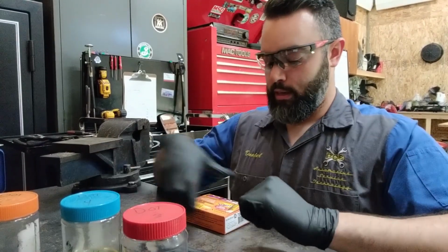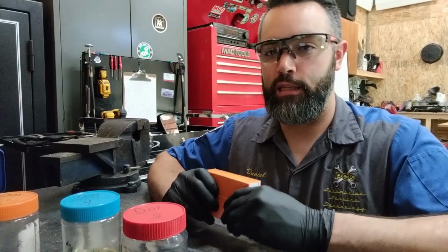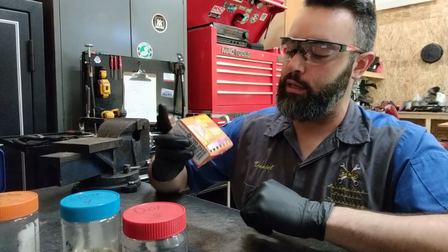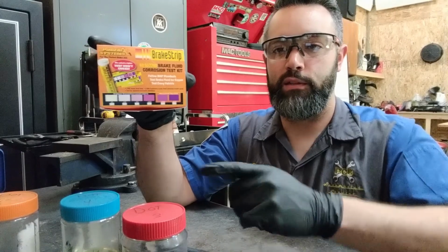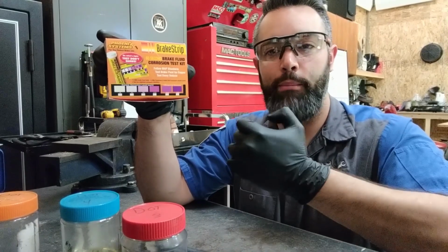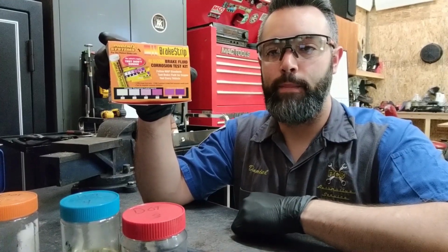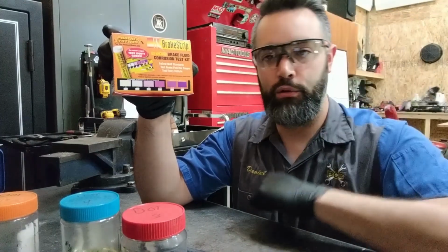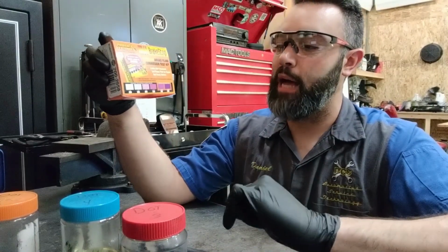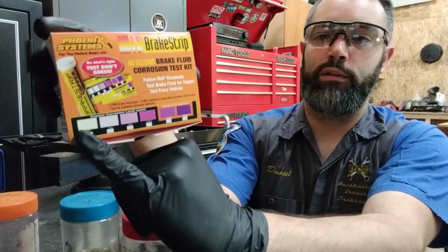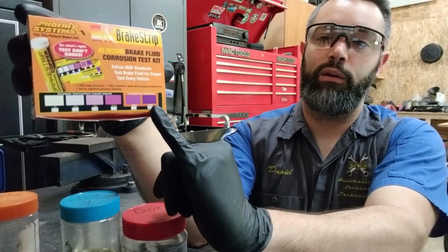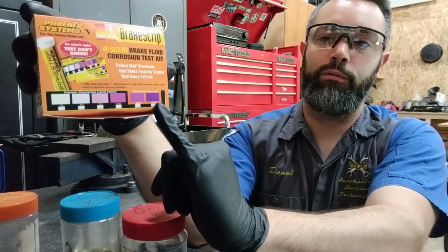Testing the fluid. There are a couple common ways that brake fluid is tested. One of which are the copper dip strips. So there's a container, I don't have it here, it's a little canister with a cap on it, and it has little test strips in it. You dip the test strip into the fluid, and there's a little patch on the end of it, almost like a felt. And that patch will change color. It'll start from the pale range, and depending on moisture content, it will darken to a darker hue of purple.